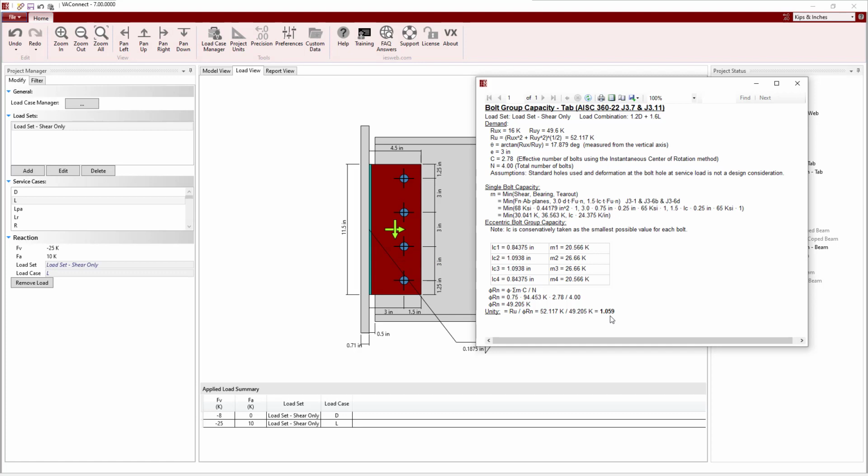The 16th edition of the AISC Steel Construction Manual contains a new section called Part 12, which is for the design of simple connections for combined forces. This new section states that single plate connections subject to shear and axial force should be designed with eccentricity e, where e is defined from the distance of the support to the centroid of the bolt group. Therefore, the eccentricity is no longer reduced for shear tabs with a conventional configuration in the load combinations where axial load is present.